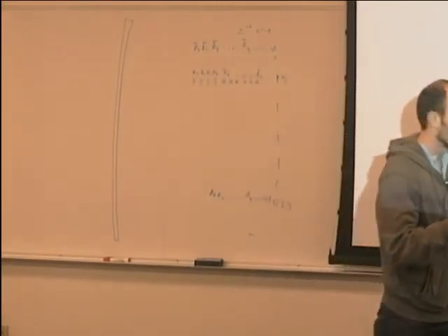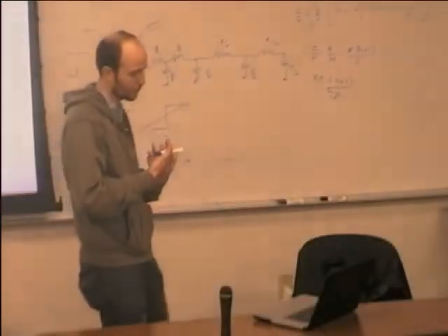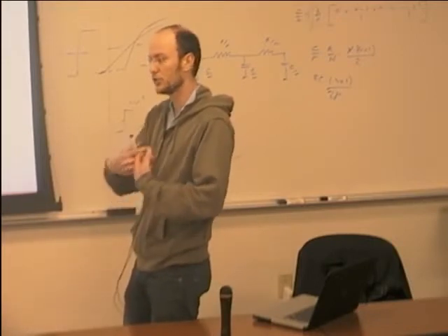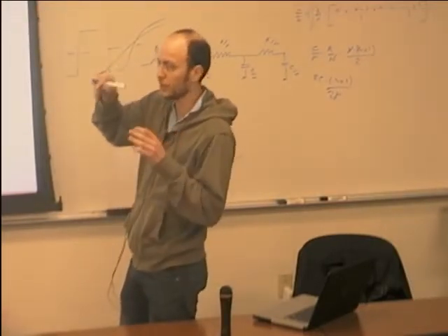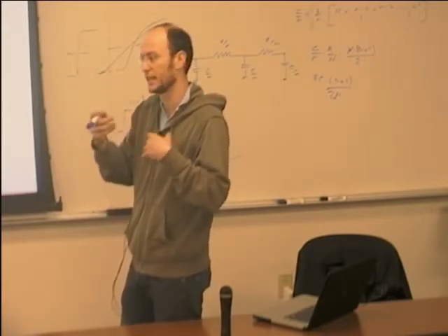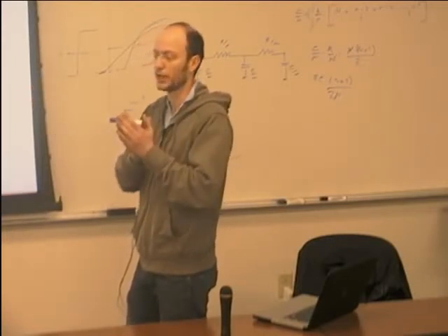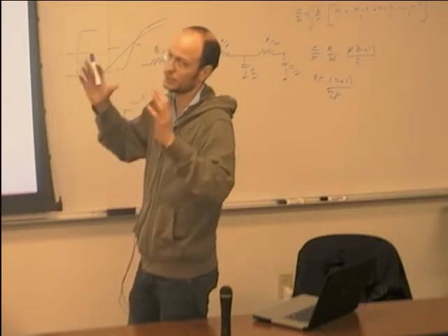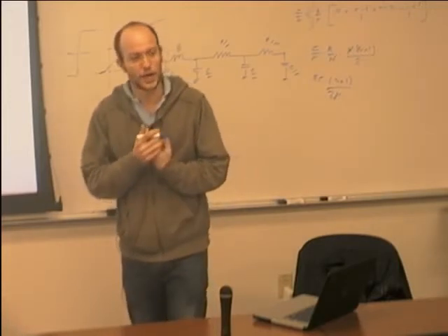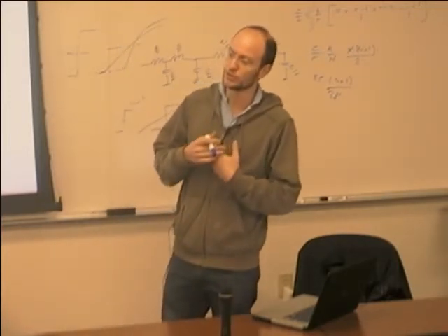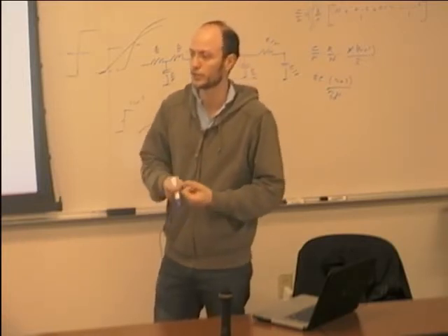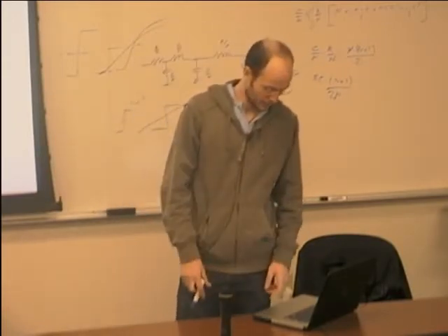So now I think the interesting part is the following. We have this decoder, and it has all these outputs. It needs to perform essentially this complex AND, right? Because if you have, as we said, the 10-bit address, it's a 10-input AND. If we have a 20-bit address, then it becomes a 20-input AND. So the question is really how we implement this function obtaining the minimum delay. Because in the end, when your computer pulls things out of cache, you want it to happen as quickly as possible. It's not that you want to wait around.